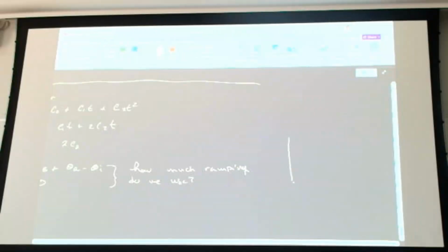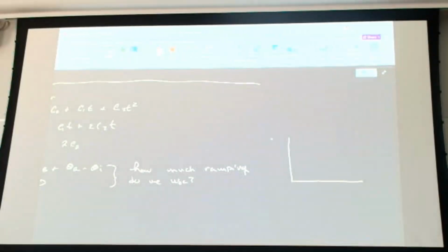So really what we're saying here, if I look at it from a theta dot perspective, again, just a simple second order. We just talked about the nth order, or how to do the blended. But what we're talking about here, and this is what you might be doing even in the lab, the idea is this is going to be our blend time. This is constant velocity. And this is another blend time. TB may be TB1 and TB2. TB1 does not necessarily have to equal